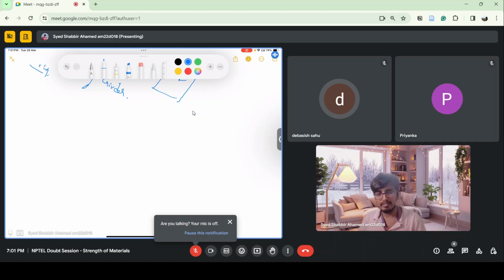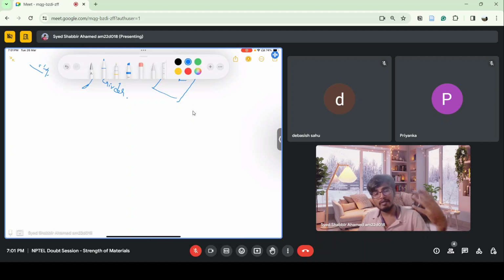Whenever you do a slab or beams or columns or pillars, whatever you call them, whenever the concrete batch is mixed, they call it batches. Whenever the concrete is mixed, they take a certain part of that concrete to the lab and manufacture cubes. If you might have seen in your college, civil engineering people will be testing those cubes. They make those cubes, and after that they check the quality of the concrete: how is it resisting load, the compressive strength of the concrete.